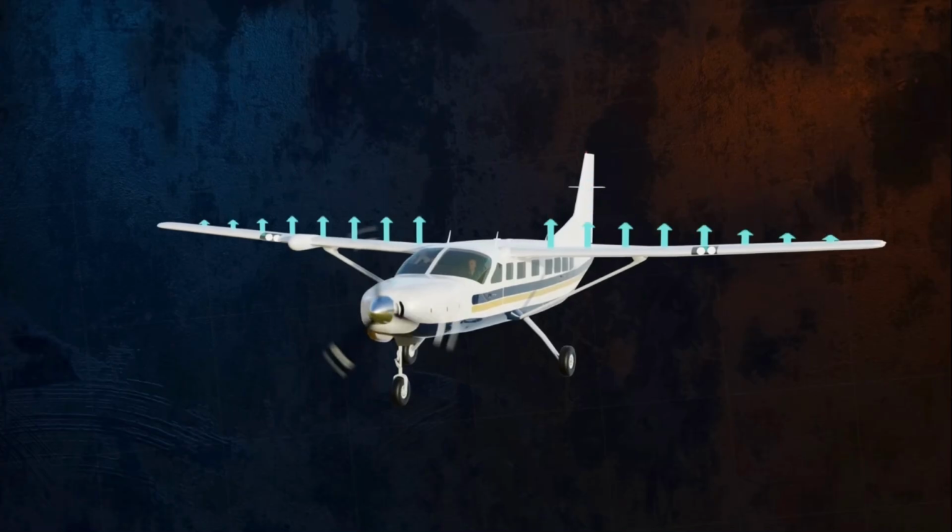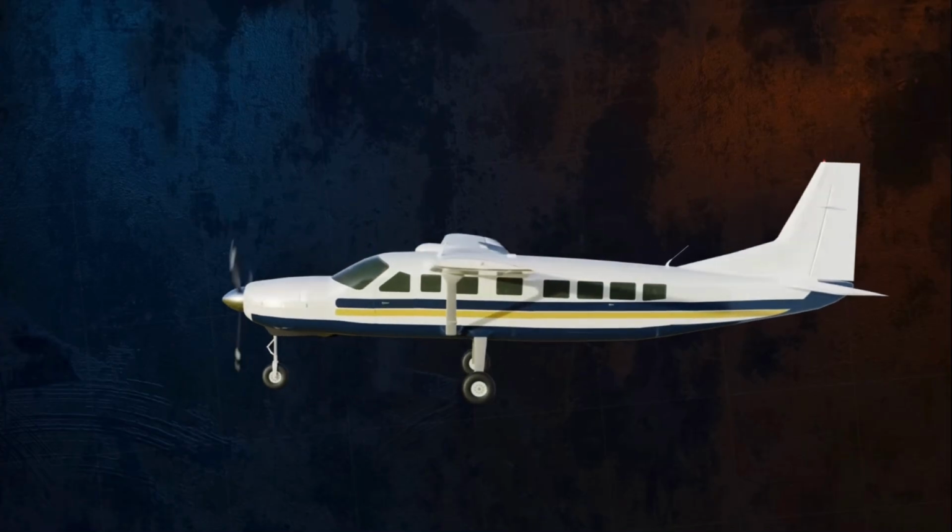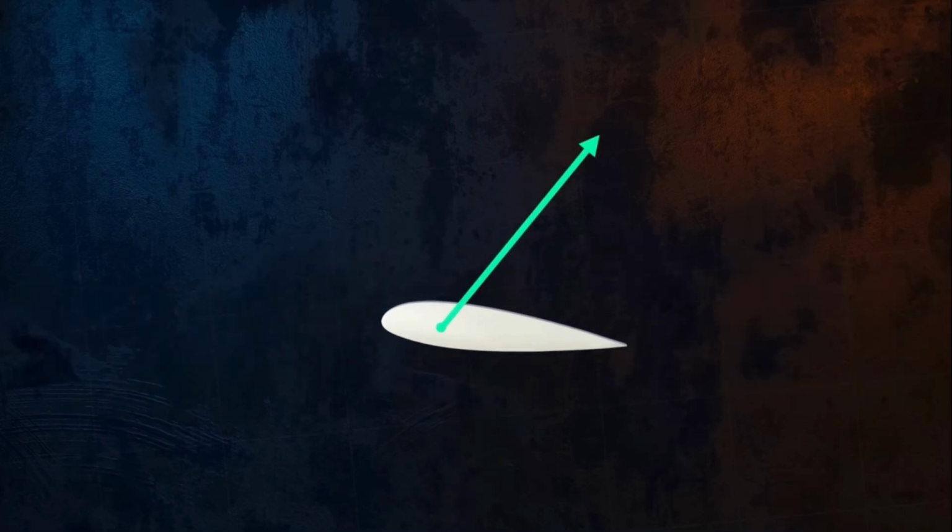When fluid flows past an object, or an object like this plane wing moves through a stationary fluid, the fluid exerts a force on the object, which can be split into a component acting in the same direction as the fluid flow, called drag, and a component acting perpendicular to the flow direction, called lift. When talking about lift, we're mostly interested in streamlined bodies like this airfoil, which are carefully designed to produce a lot of lift, but to minimize drag.